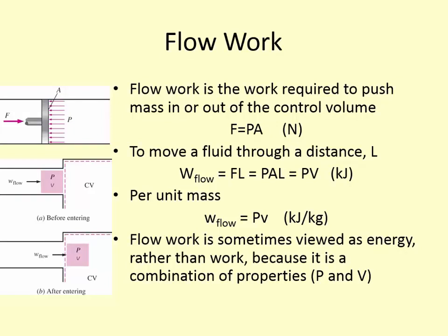Flow work is the work that's required to push mass in or out of a control volume. So if we're moving a fluid through some distance L, the flow work is equal to the force times the distance, or F times L. I think this laser pointer works now. Yeah. And this force, for fluids, is often due to the pressure of the fluid.